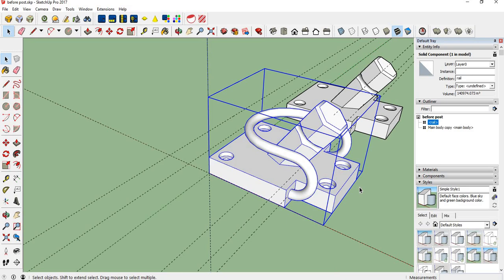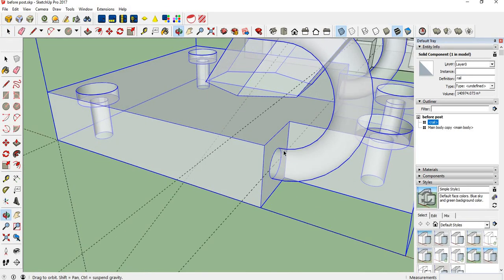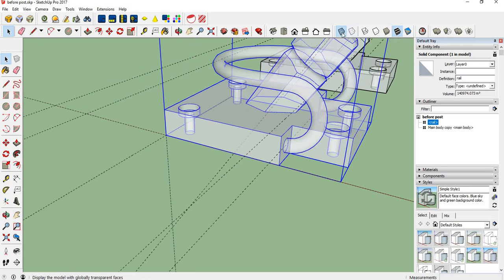Okay, so it went ahead and completed the process. I used Solid Tools on this one. And notice now it's one solid component and there were no errors. If we go to X-ray, notice how the insides, those extra pieces, those weldments, are not there anymore. So now it's just been joined at the hip right there, so to speak.